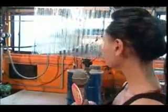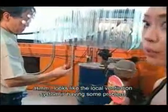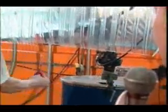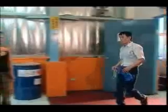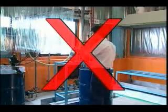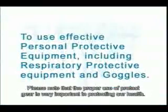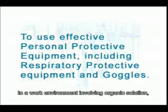Looks like the local ventilation system is having some problem. Let's see what Mr. Wang will do. Oh, so Mr. Wang is putting on a protective mask. Is Mr. Wang putting on the correct type of mask? Note that the proper use of protective gear is very important in protecting our health. In a work environment involving organic solution, a gas mask should be used. Let's see the proper way to put on a gas mask.